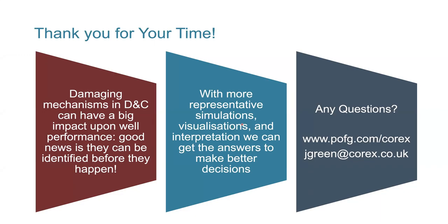Sure, I see 3 questions there. So I'll just answer them in the order that they have them. First up, we have Marcelo's question, which is, do you think the industry has to move forward to find a better way to test the compatibility of the drilling mud with the reservoir? 100%. Obviously, what we have to be striving to do is to be constantly finding a better way to test the compatibility. As I said, you can start off extremely basic, take a bit of ceramic disc, try a leak off test against that and see if the mud is good.